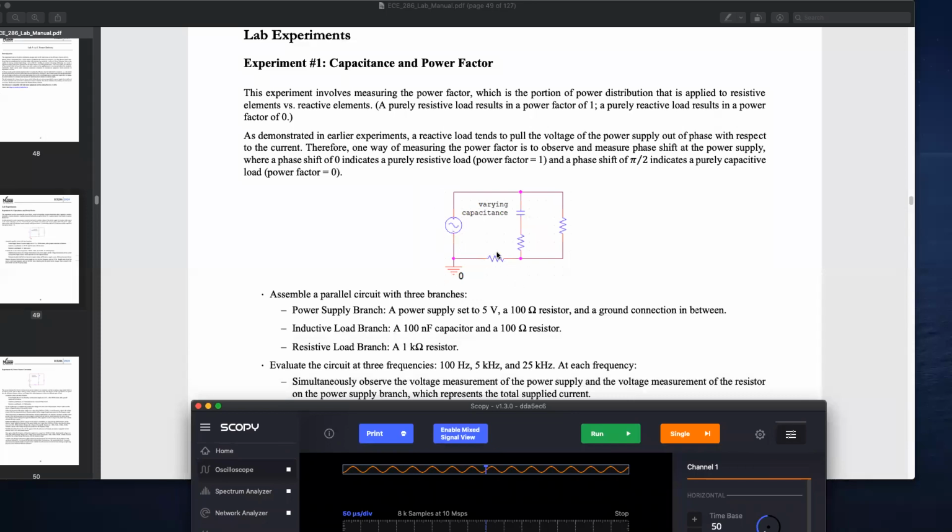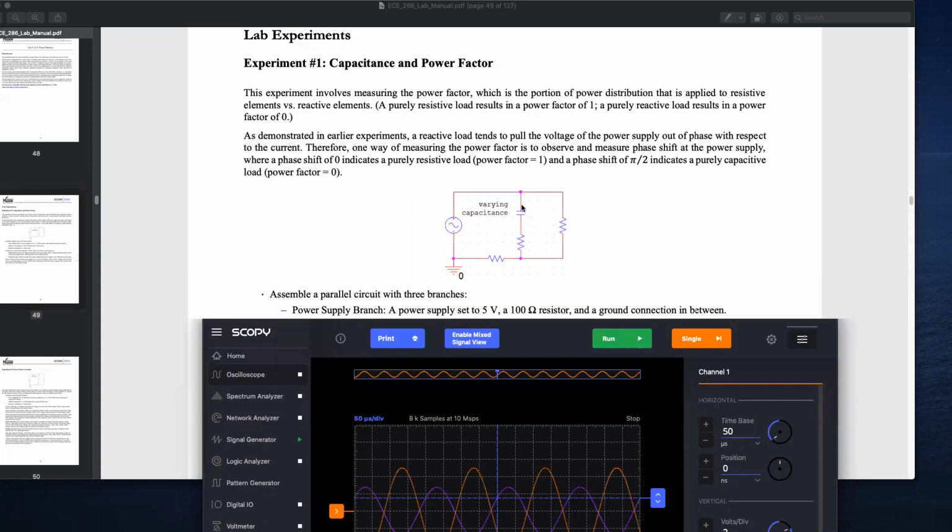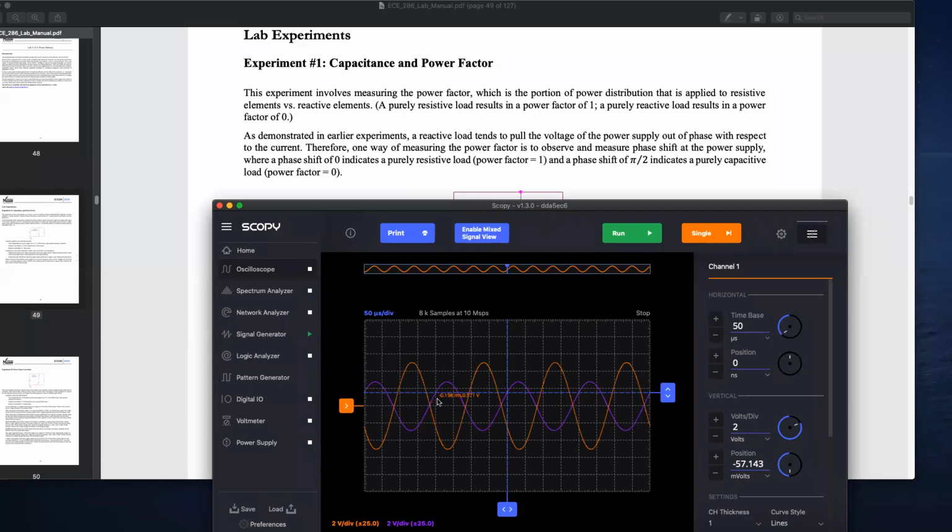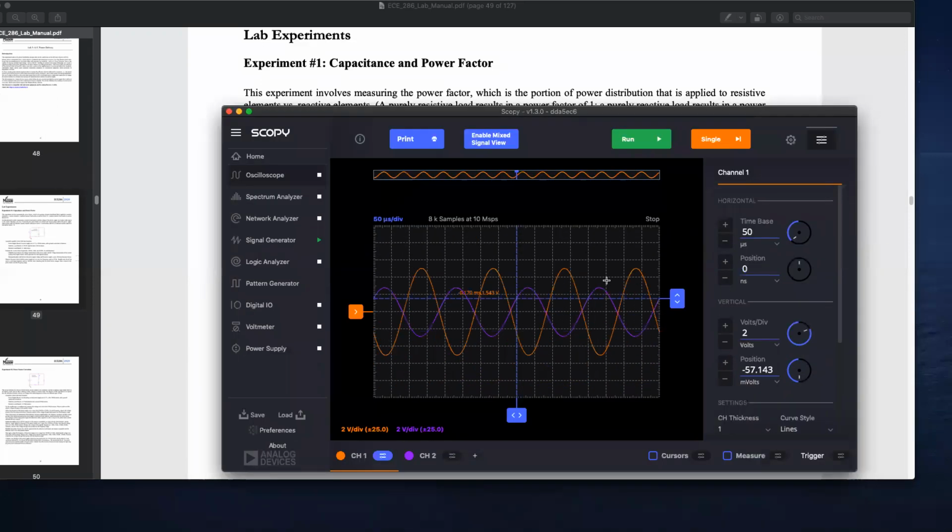If you divide the voltage measured across the resistor by its resistance, you get its current. So let's just think of it as current. The purple waveform is essentially current, if you divide the amplitude by 1K, because that's what my resistance is.